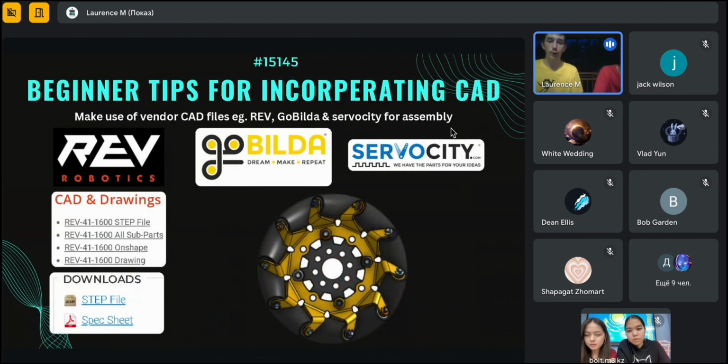So, beginner tips for incorporating CAD. One of these is making good use of the REV, goBILDA, and ServoCity websites. When you go on, you can search for the specific part that you want to use in your actual robot. Often they will have a STEP file or engineering drawings of that part that can aid you in the modeling process. Essentially you can grab them from online into your CAD, so you can assemble your robot with your vendor parts in your assembly, which is really helpful for knowing your scales and ensuring that the parts designed in CAD are going to work in real life.